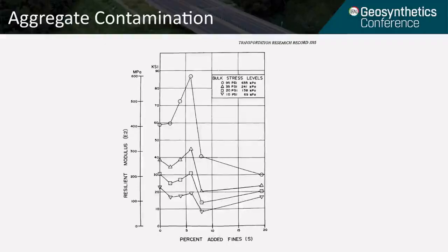So the roads are treated with a geosynthetic, but the other areas aren't. And what this can lead to is contamination from equipment that's accessing the untreated sites, eventually using the roadways and causing contamination from the top down instead of from the subgrade up into that unbound aggregate layer.